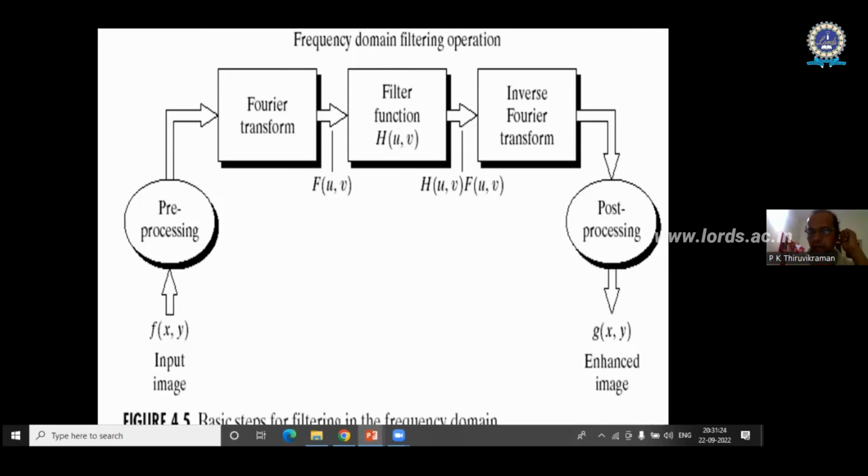Now, the confusion here could be, what about the operations involved in the Fourier transform and inverse Fourier transform? I do fewer operations for the multiplication as compared to convolution, but what about the operations involved in taking the Fourier transform and inverse Fourier transform? Actually, if you use the fast Fourier transform algorithm, the number of operations becomes less, and you can show by a detailed calculation that the total number of operations is less than doing it in the spatial domain.